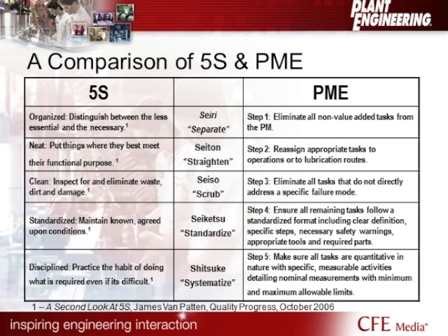So when someone gets one of these preventive maintenance tasks, they know exactly where to find the details that they need. And I'm not suggesting that every one of the PM tasks has to look like a training document. But it definitely does need to call out things like torque specs. It may need to call out belt tensions, alignment standards, all of those sort of things that I probably don't commit to memory. So I want to make sure those are included in that PM task.